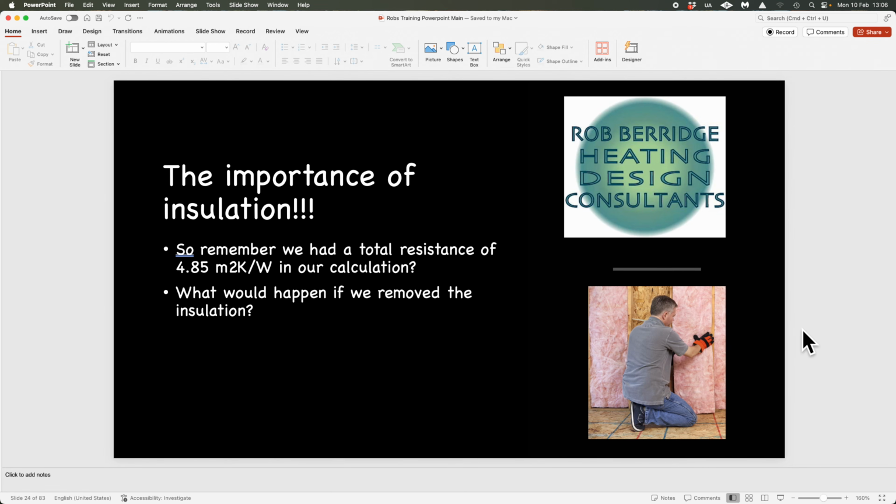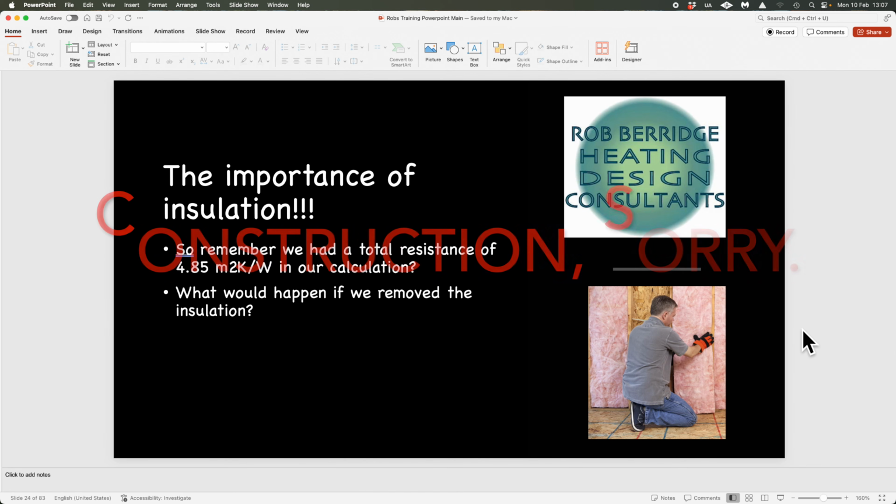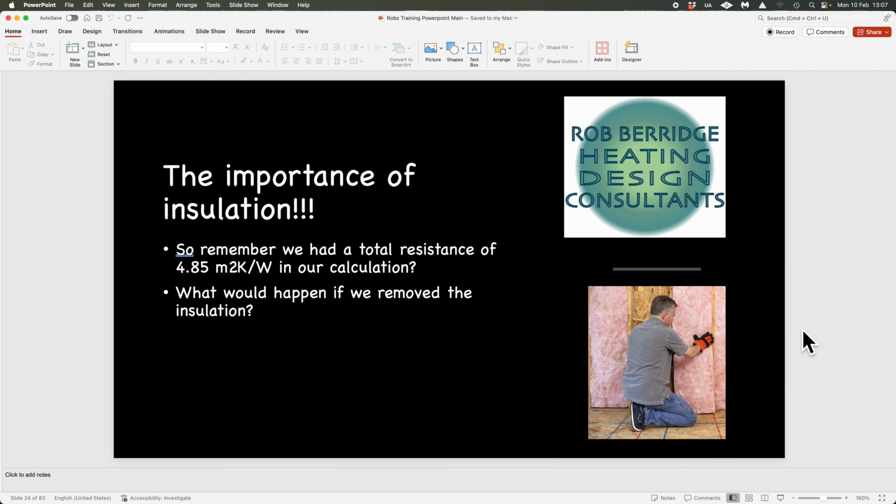You take your first drill through the wall and you hit the cavity, and without thinking, you pull that core out, and before you know it, you're knee deep in snow, or knee deep in polystyrene balls, as we've all seen before. Now, that is compromising the integrity of the resistance value of that product. Imagine if you're right above that hole that you've just made in the wall, you will have created a massive V shape where all those polystyrene balls for meters and meters above in that cavity have just drained out into this Y-shaped funnel, look, as it's all poured out of this hole in the wall.